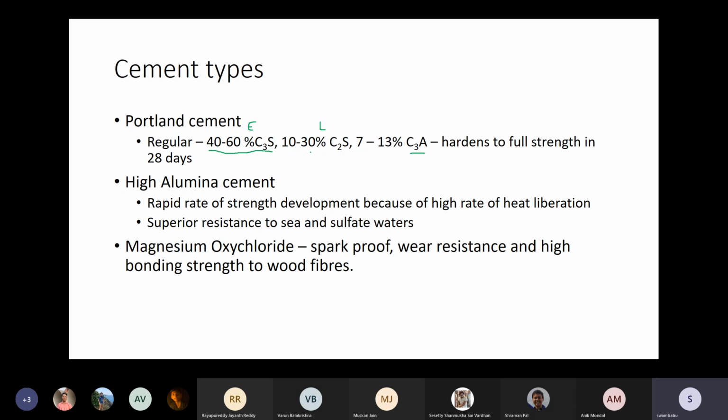So that's why, in your household construction, as soon as you apply it, you will see in a few hours, not even a few hours, it will get strengthened, it will get hardened. But to get the full strengthening, the full effect of all these, C3S and C2S, it will take almost 28 days. That's why, when buildings are constructed, they say you need to do regular watering. Those buildings which are not regularly watered will not reach the full strength, and you will see cracks in the wall very fast because of this C3S and C2S relative contribution.